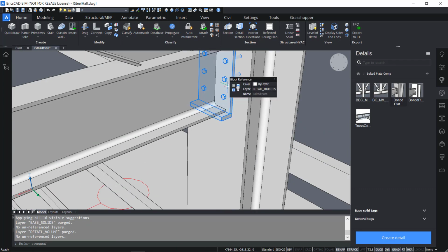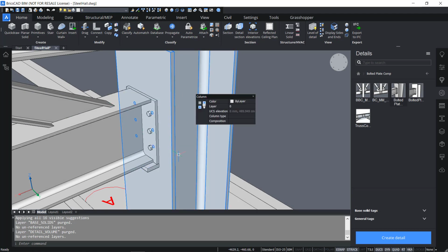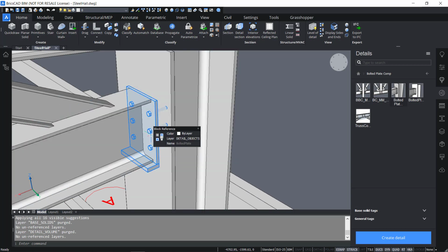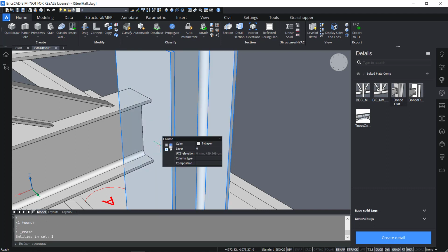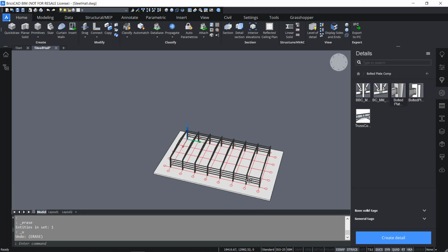And then you will see it's propagated all the way until in our drawing. And the holes are automatically made. If you delete it, again, it's a smart hole. If you hide it, you still see the hole. If you delete it, the holes go away. So it's a smart hole that restores itself once it's not present anymore.